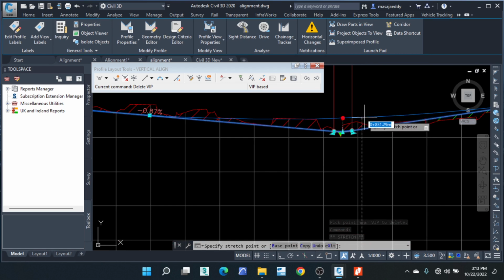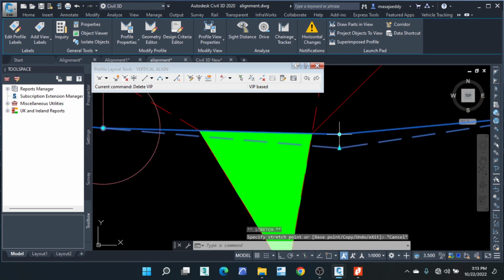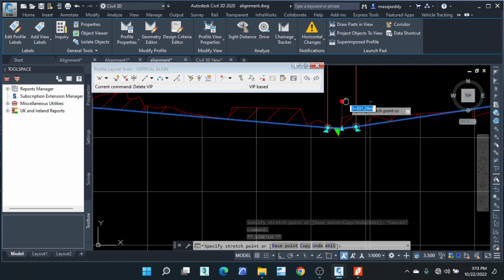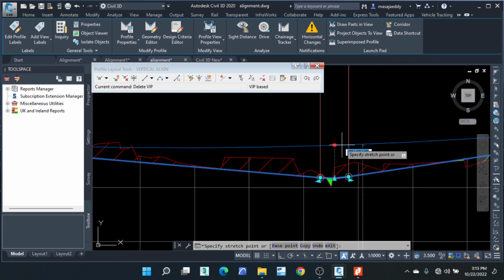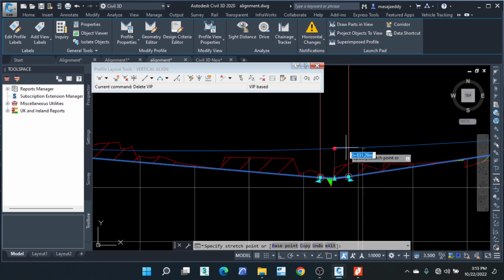So in this case, at the low point, I'm going to adjust the... I'll drag this midpoint of the curve, this round bit, above the existing ground. So we are assuming at this point we are going to have, say, a 900mm culvert. So our fill, at least, would be greater than 3/4 the size of the culvert, which is at least more than 0.8 meters at this point.